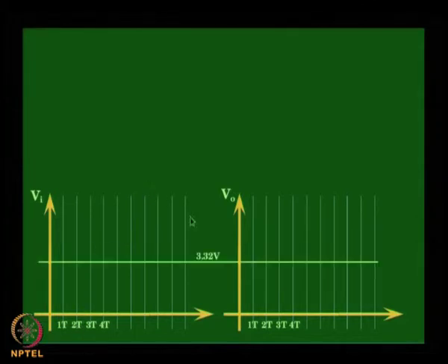Now, the final settling value of the output is 3.32 volts. That is, if you provide at the input 3.6 volts TTL compatible, as we saw in the previous slide, we should get at the output 3.32 volts immediately, because we have an output of 300 ohms termination and